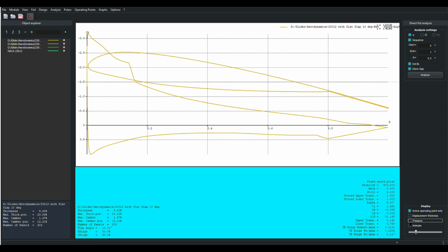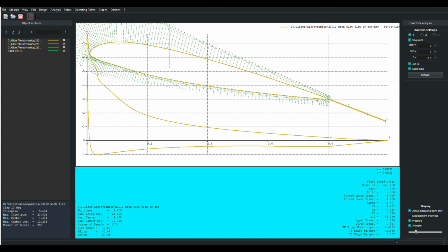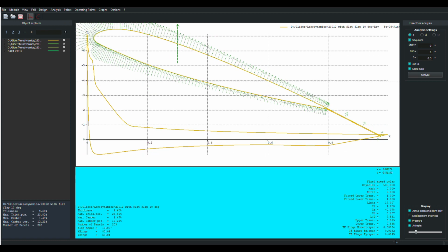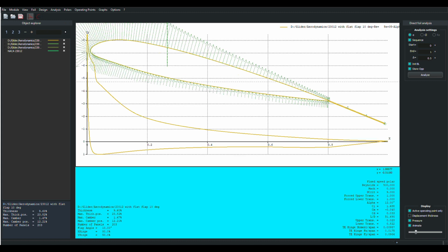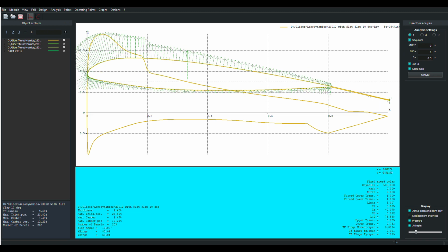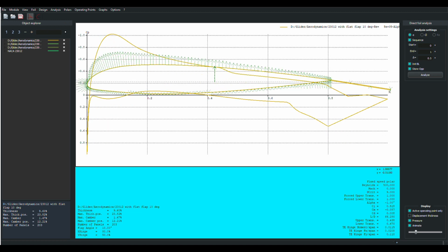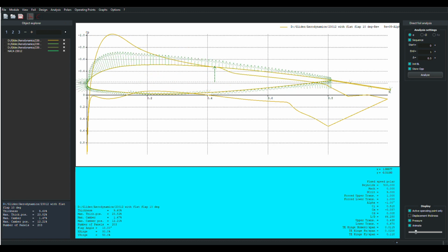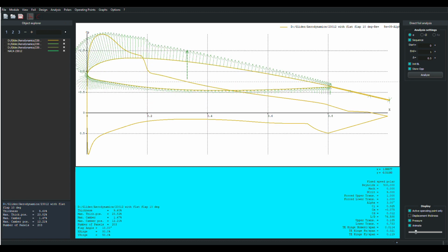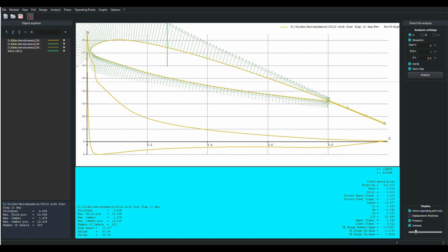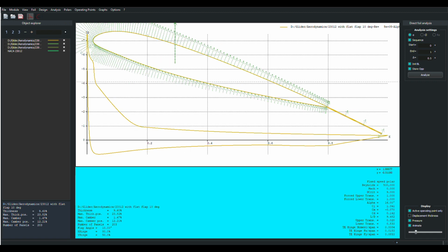I'm going to turn the pressures back on here. We'll let the animation run. You can watch this go through its deal here, because with this 10-degree deflection, we can run through this, and it has enough solutions so we see that we never develop that pressure spike at the leading edge, yet we are getting a nose down pitching moment. We'll go look at that curve in a minute. It's not as strong as it is if you have a nice thick trailing edge flap, but we eliminated the other problem. So, fascinating.